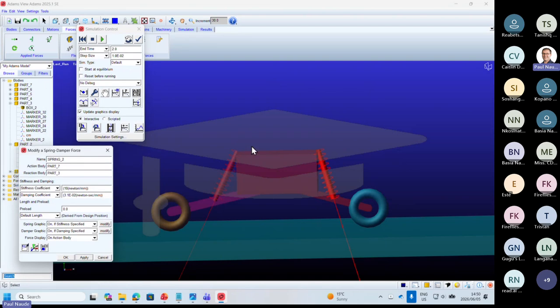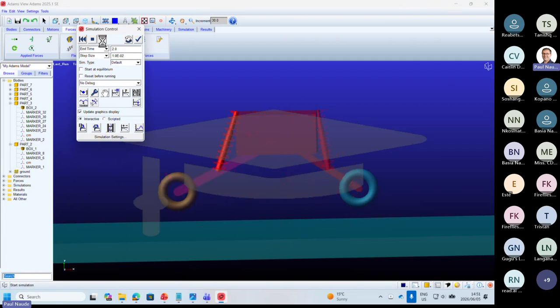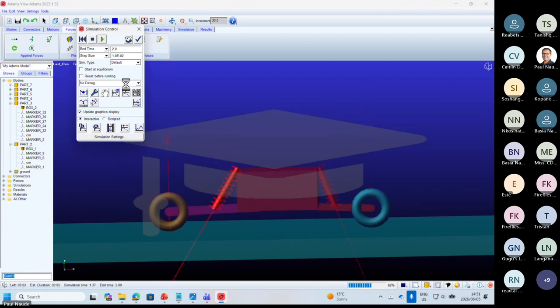You did see that it's extremely wobbly, and that is because I didn't increase the damping coefficient. So this is a spring damper system. Now in your Mars rover, you'll have to represent what you're going to build. So you're probably not going to have a damper system in there, but if you do, you'll want to know what this value should be. I'm just going to increase this value. Same for this guy, make it a bit more stable, and let's see. Okay, I think that can actually work.